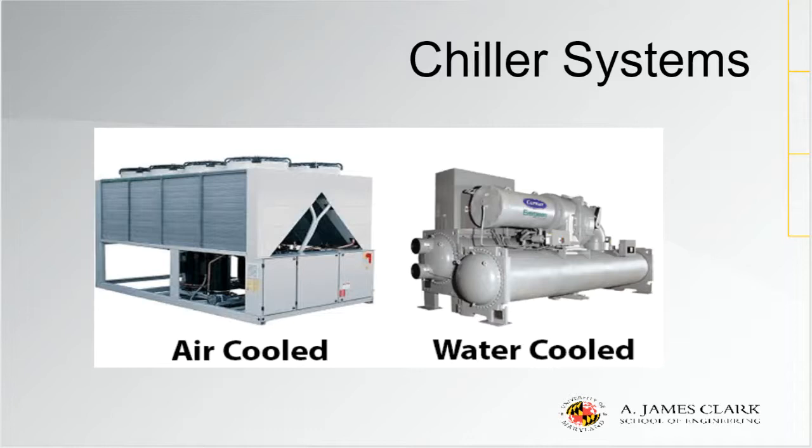One of the main components of our model were the different chiller systems that we use. So what's a chiller? A chiller basically removes heat from a load and transfers it to the environment. The two main chillers that we would use in this model are air-cooled chillers and water-cooled chillers. Basically, water-cooled chillers use a water reservoir in a refrigeration cycle to remove heat. It utilizes cooling towers, which leads to higher efficiencies than air-cooled chillers. They're also generally smaller than air-cooled chillers and last longer. One of the downsides is that they have high water consumption.